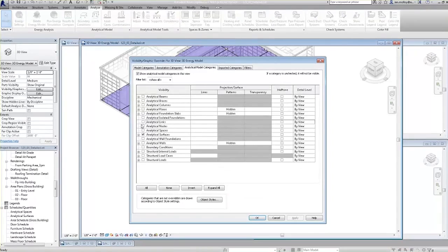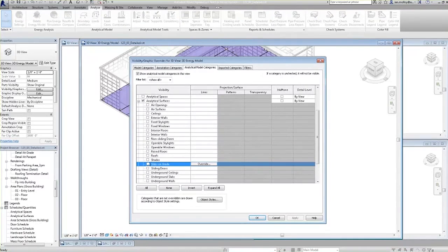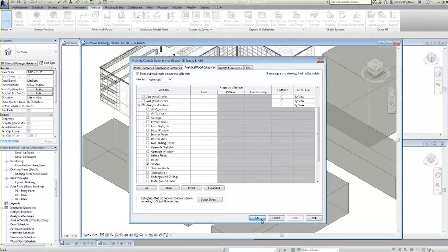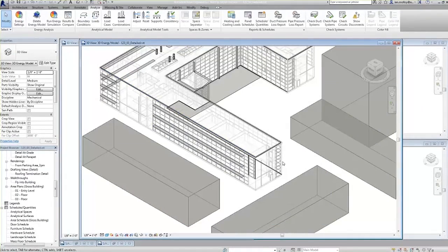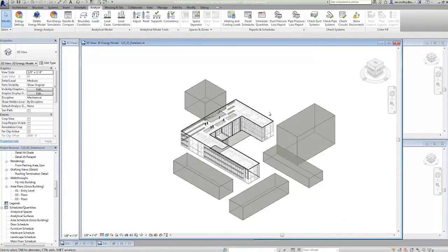We can also do things like, another one I really like showing is where there are shades on the building. So here you can see the surrounding shadings, and these are all shades on the building. So that essentially gives you an overall overview of the new energy model visibility, the combined mode, and the way we're running the simulations on energy cost range. The one thing I just want to repeat again about the combined mode is that you don't have to have both. You can have any mix. It will work with whatever mix you have, and it will determine. It's basically got all the knowledge that an energy modeler normally has when they create an energy model embedded in it, and it just uses the physical objects that you have in the model.